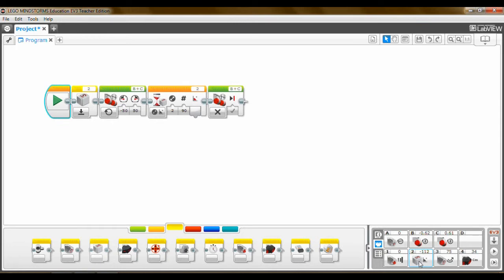That is over 90. There are variables that affect turning with a gyro. It takes time for the signal to be sent out, so 90 degrees will usually not work. Width also affects it, so you'll have to experiment to find 90.